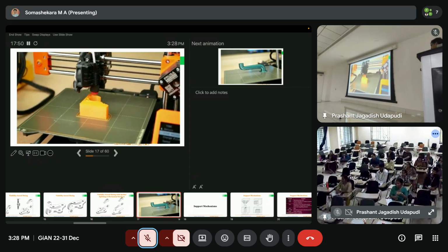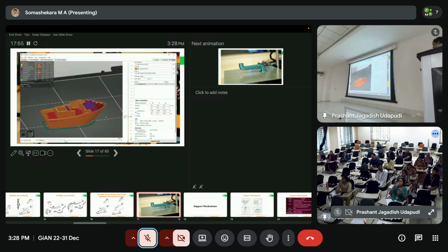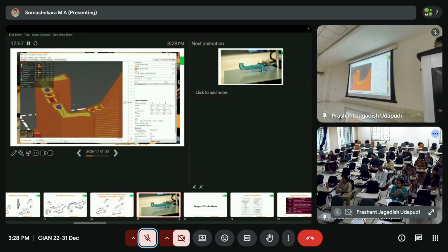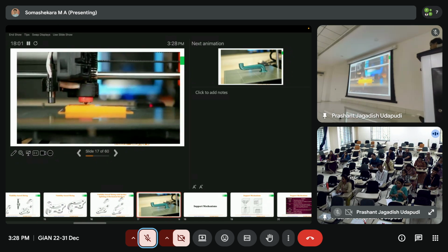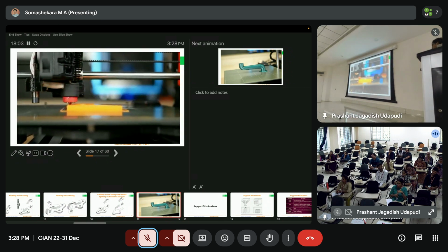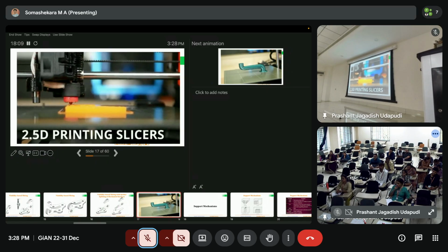Current 3D printing slicers are done. What I mean with this is that even though they are slicers for 3D printing, they simply stack two-dimensional layers on top of each other to form your final part. There are basically no movements within the G-code instructions where all three axes move simultaneously. That's why current 3D printing slicers are rather 2.5D slicers.